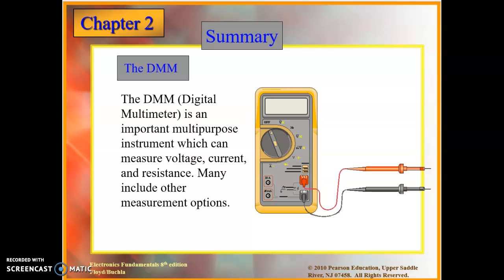We're going to continue with understanding how to use a digital multimeter. So we went over how to measure voltage, how to measure current, and that we have to always look for the straight bar on top of the letter to make sure we are doing DC. If we pay attention and look, there are some curly ones, and that stands for alternating current or AC, and this is not what we are going to be measuring in our lab.